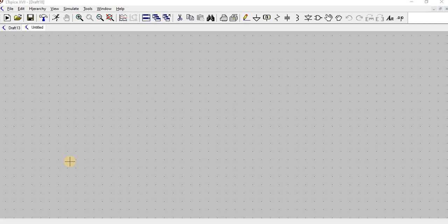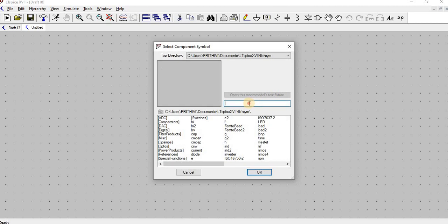Now to see the performance of the common emitter configuration, we will take the emitter as the common terminal between the base and collector. We will apply the input at the base-emitter side, and take the output at the collector-emitter side. Before going into the performance, at first we require a basic BJT transistor. We will do it for an NPN transistor.